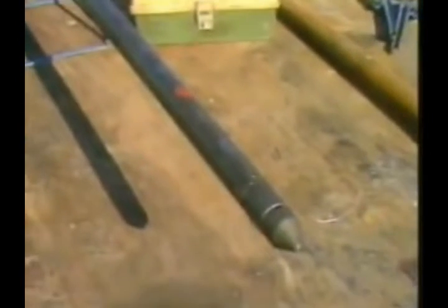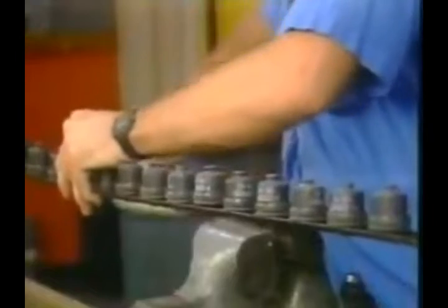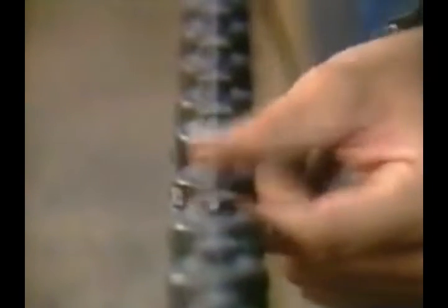Also, the delivery system for placing the shaped charges at the proper location via wireline may be categorized as one of three possible types. Retrievable, consisting of a cylindrical hollow steel charge carrier, which is retrieved after firing and may then be discarded, as in the case of scallop guns, or reused several times, as in the case of port plug guns. Semi-expendable, in which case the perforating charges are conveyed into the well on a retrievable metal or wire carrier. Or fully expendable, where the charges and carrier linkage disintegrate on detonation, and only the wireline is retrieved.